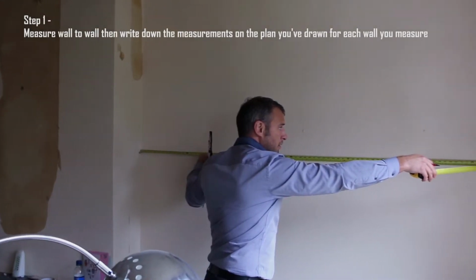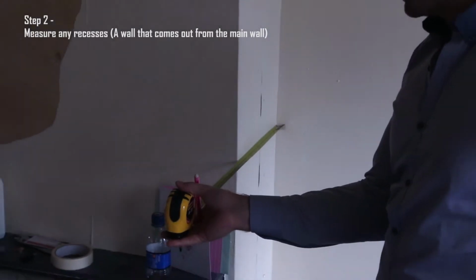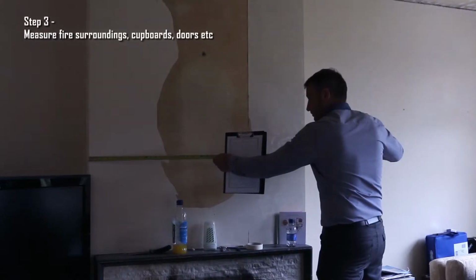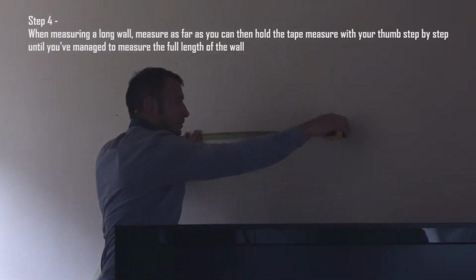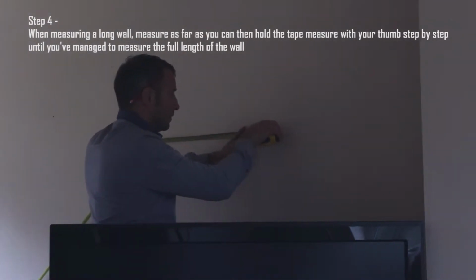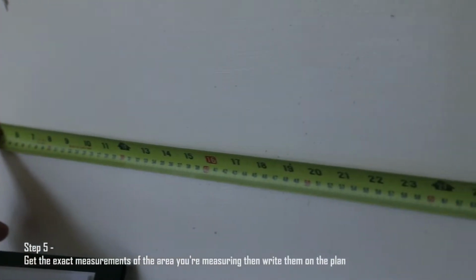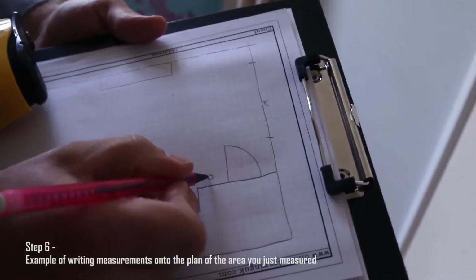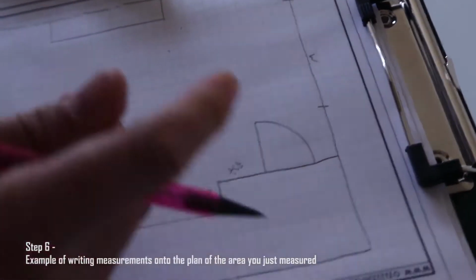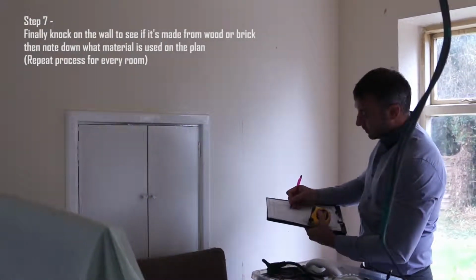All we need to produce the size of the inside is the lengths and recesses jutting out, as you can see there. Every length of wall, every length of window, to the nearest 5mm is absolutely fine, right alongside the dimensions that you measure. Just check what the wall's made of. A simple knock will tell you whether it's solid or hollow.